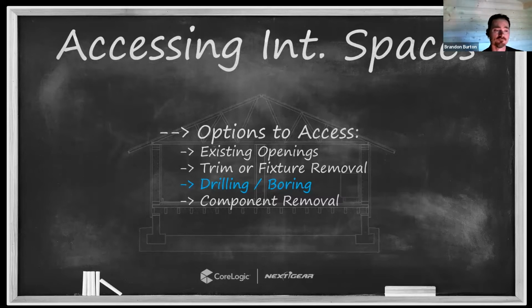Then last but not least, if none of the above is going to work for me, we've got complete component removal, right? And remember what we mean by component. This comes from an earlier episode of Technically Speaking. We have assemblies, right? A wall is an assembly. And then we have components. The wallboard on a wall is a component of the wall assembly, right? So we may be able to remove components. For example, if I've got wainscoting on a wall and I want to make sure I have direct access to what's behind it, maybe remove the wainscoting if that's the best option, if that's the only option, right? I would much rather remove the trim, make my access behind the trim, and then replace the trim than remove all the wainscoting. So that's, again, the reason why we order this in this list of operations.